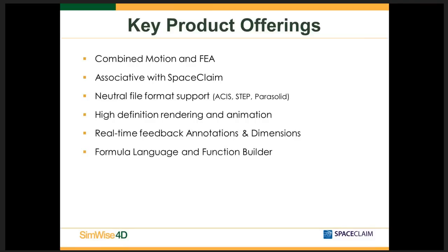We have powerful formula language and function builder capabilities in terms of bringing data in through Excel, let's say table data, and writing your own mathematical functions. We have a wide array of capability in that regard. We also have an API for customizing the program to tailor to your needs. If there's a certain task that you do on a day-to-day basis, you can customize SimWise to help meet those, stay within that envelope of what you're doing, and automate your process of building your model and running your analyses.